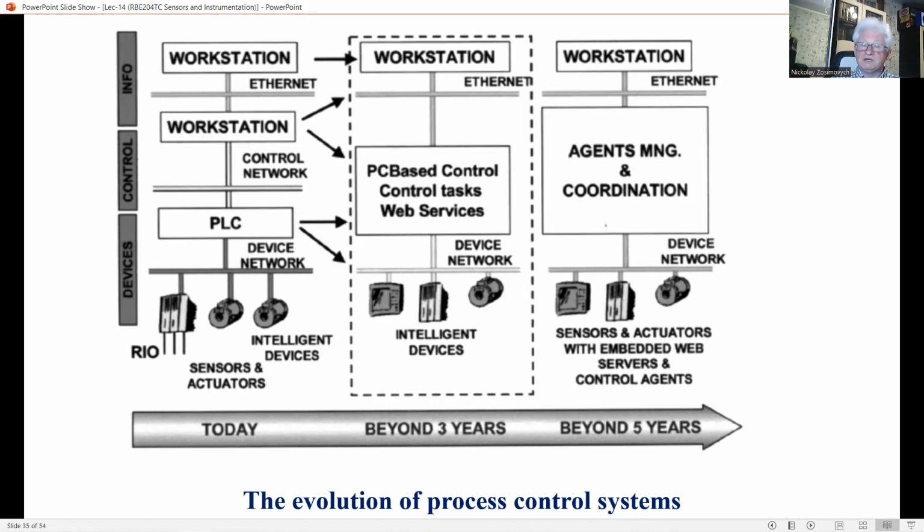In feed-forward control, unknown inputs are measured, and that information, along with desired input, is used to generate control signals that can reduce error due to these unknown inputs or variations in them.